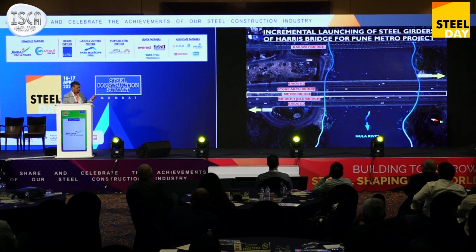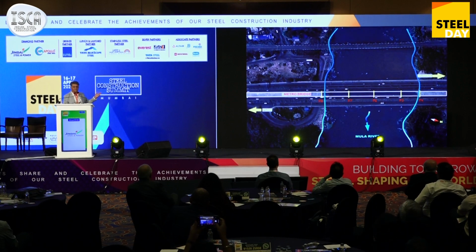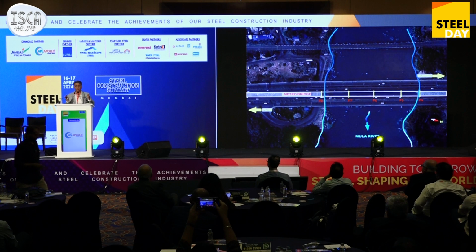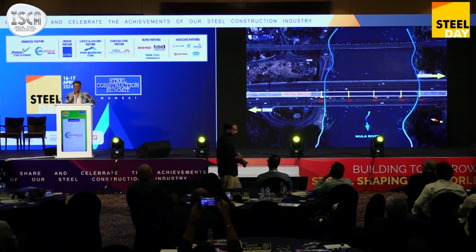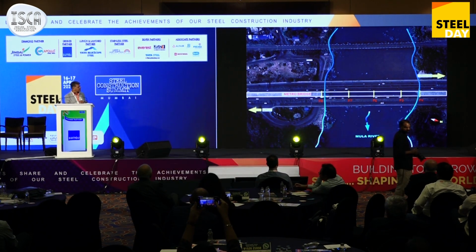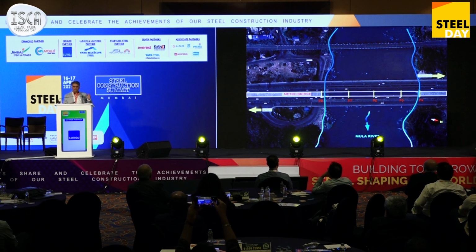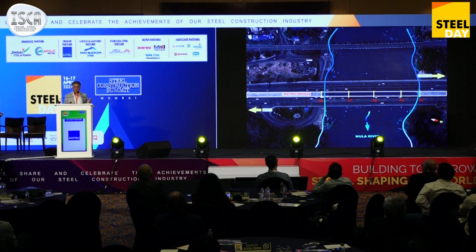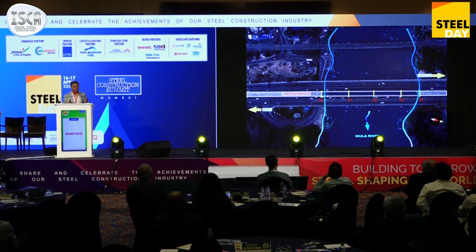And further to add to that, the bridge is designed as a simply supported bridge. Simply supported means every pier will have an expansion joint, meaning each unit is cast in between these piers. So there is no chance to take any construction material or equipment on the existing bridges, because all the bridges, including the arch bridges, are load carrying capacity limited bridges.